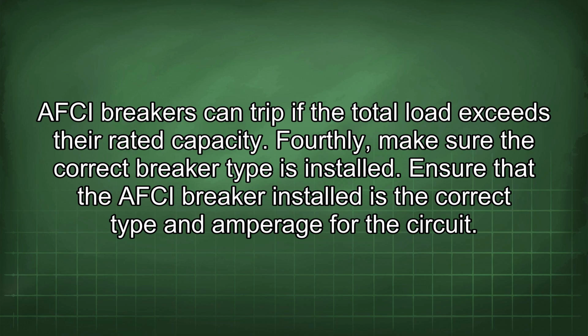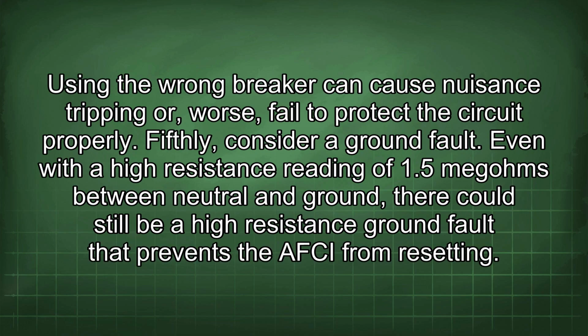Fourthly, make sure the correct breaker type is installed. Ensure that the AFCI breaker installed is the correct type and amperage for the circuit. Using the wrong breaker can cause nuisance tripping or, worse, fail to protect the circuit properly.